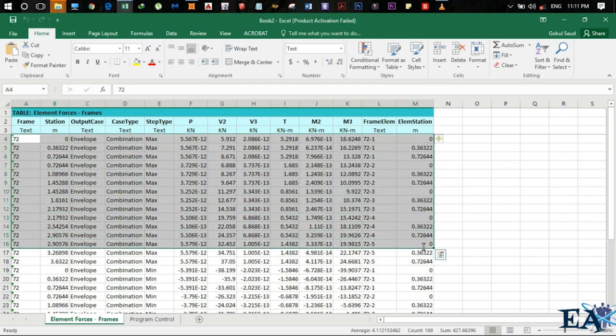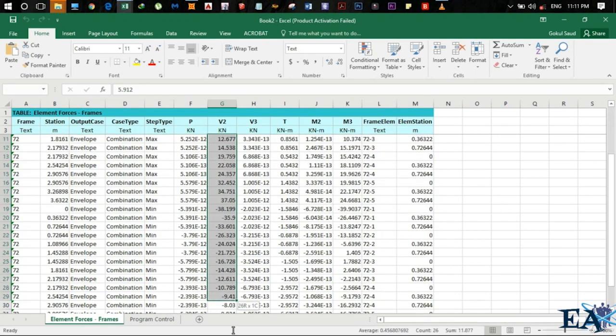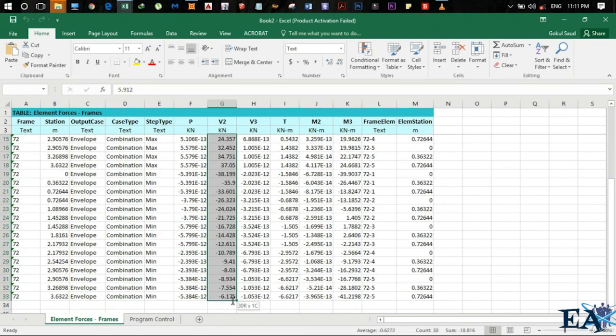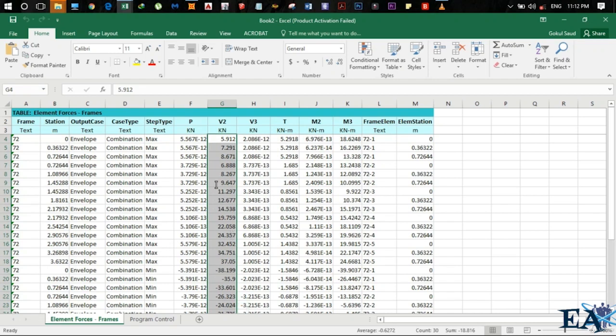here you can see the data from SAP has been exported to Excel. Now, if you want to just get the maximum value out of it, you can just use the formula in Excel and get the maximum value. Similarly you can do this as well, right? This is another method of getting the maximum value. One different method I have already explained in previous chapters, right?